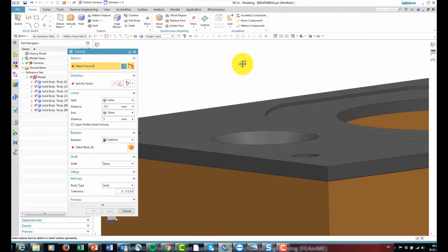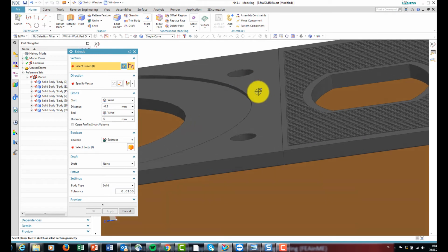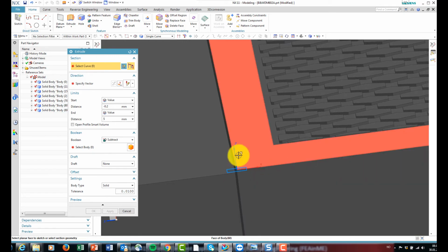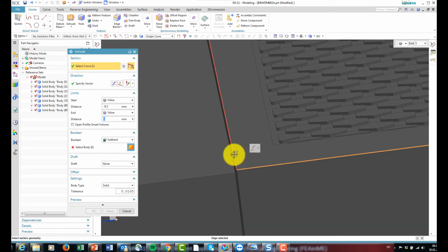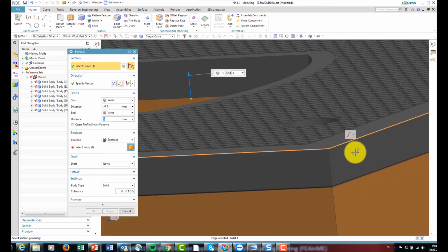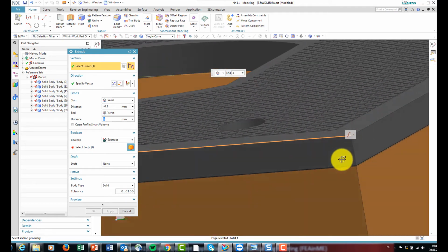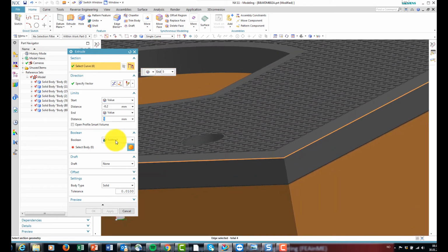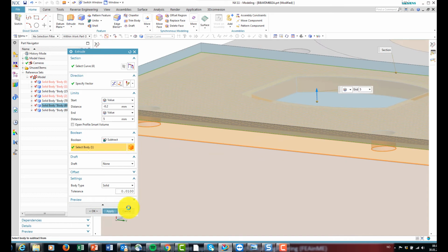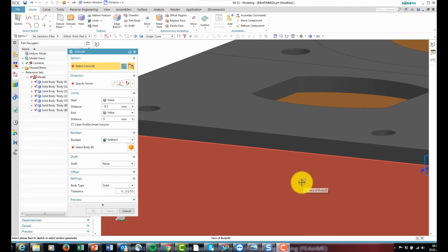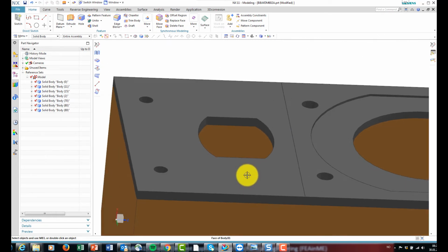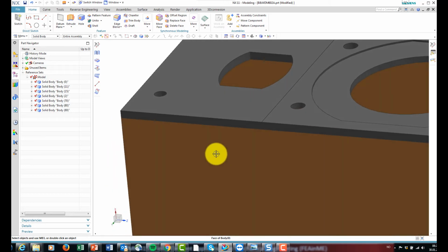There we are. You can see that the extrude command sliced off the front pattern. You see it's a little bit thinner, but that's okay. And now I do the same with the other front pattern, like this, and I subtract from this one. Apply. There we are. Now you can see that I've sliced off the pattern completely, and I got a clean front, which is simple to mesh.